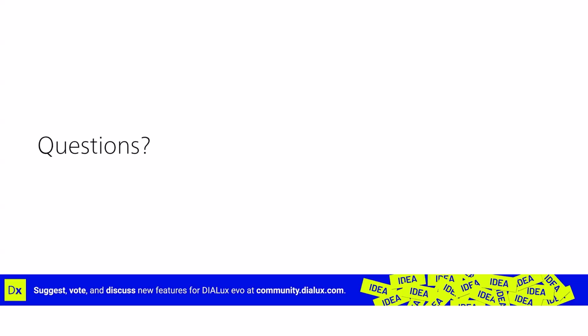We are still on the improvement of the DIALux import, and maybe you would like to add some things about it? Yes. On the technical side, of course, you're absolutely right. Nevertheless, if you want to check or if you want to create a good IFC file, please have a look at the different levels, at the different stories. In my opinion, this is the most common failure out there.